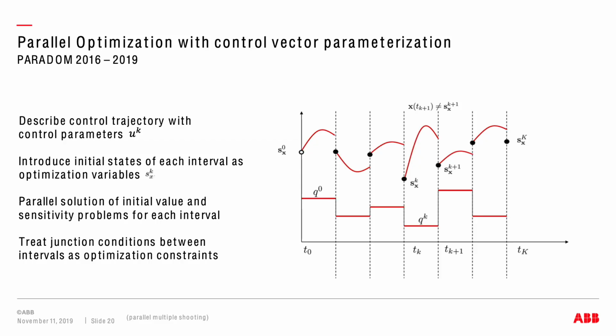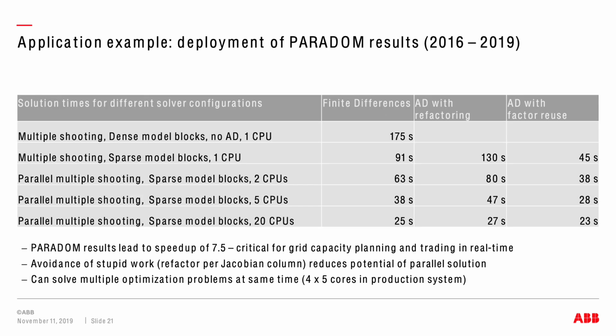And then, as we apply multiple shooting, there is a nice way to calculate this in parallel. We have the multiple time steps for all the blocks that I showed you before. I said that the model has 80 variables in an equation system. And if we are asked to solve this model over a time period, then we can do this in parallel. And at the end, we have to solve a large linear equation system, where we can again employ parallel equation system solvers. And we iterate between the equation system solution and the simulation of the model with parallel computers.